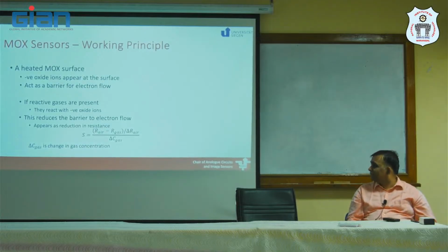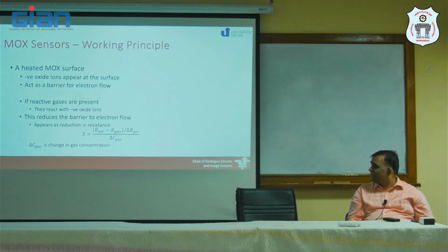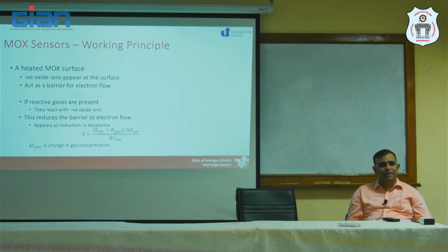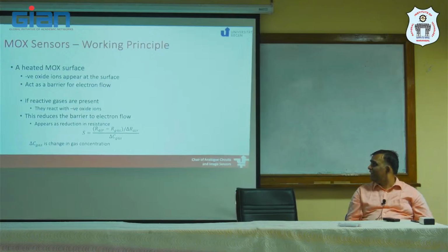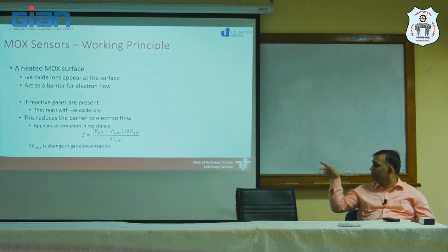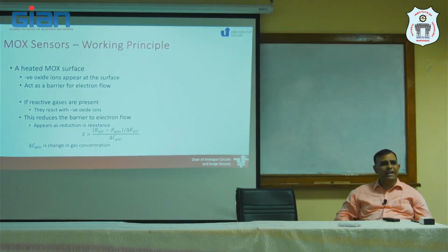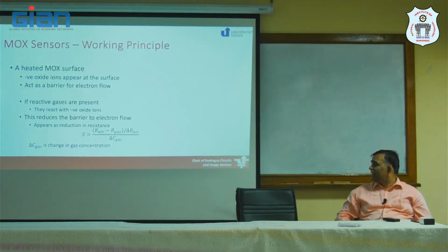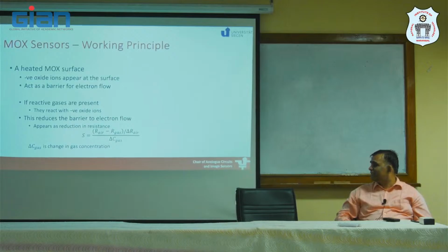Typically, the reduction in resistance, as you say, we are looking at change in resistance when the metal oxide reacts, is fairly linearly proportional to the concentration of the gas which you have. So if you have air, if you look at that, it's a fairly decent reduction.